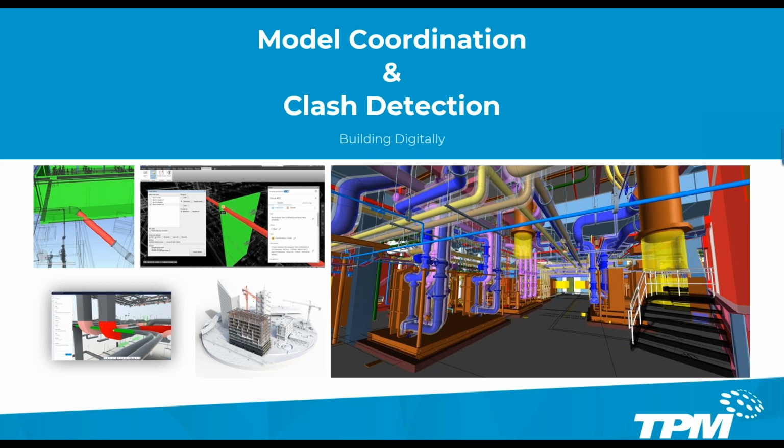What the VDC model coordination process is really, we take all of those models from the design teams and we aggregate them. We incorporate trade partner information and models as well into that. And we run clash analysis. This is done often through Navisworks or the ACC platform. This can be done at the early stages of a project, so you can identify any major design issues. I would consider that kind of the design coordination, where it would be pretty high level, looking at your large clashes, making sure you're not having any major structural issues.